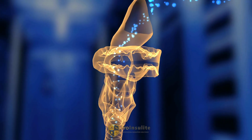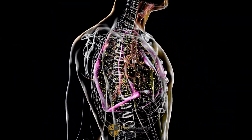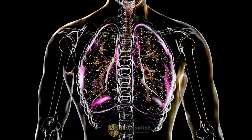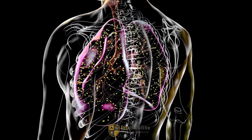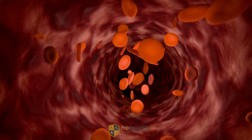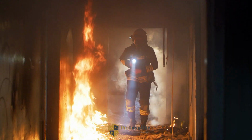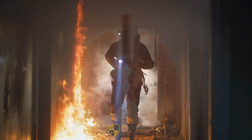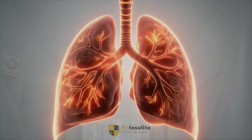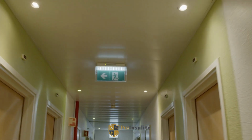Smoke introduces multiple hazards at the same time. It is toxic. Fire gases such as carbon monoxide and hydrogen cyanide impair oxygen transport and disrupt cellular respiration, even at low concentrations. It reduces oxygen availability. Fire consumes oxygen while combustion products displace breathable air, creating rapid asphyxiation risks. It is thermally aggressive. Smoke efficiently transfers heat and irritants capable of causing severe airway injury. It severely limits visibility. Disorientation and delayed evacuation significantly increase occupant risk.